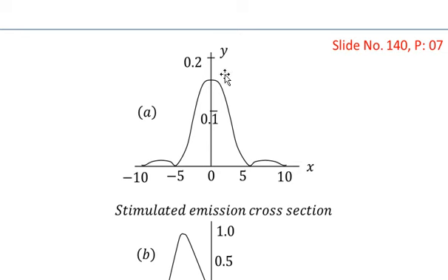This is the main lobe of the power spectrum, and this one is the first side lobe. You can see that in the main lobe, the power spectrum indicates that the main frequency will lie in this region. The other frequencies are also present. So a full range of frequencies, in the range of x going from -5 to +5, are present in the spectrum.